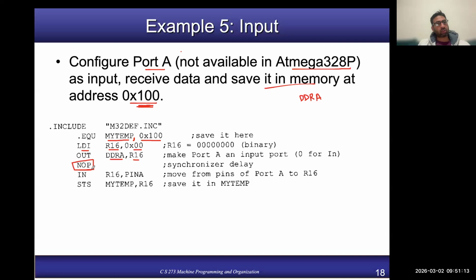So that's why we need to insert one NOP instruction, which basically means putting a delay of one clock cycle. And after that, you are reading the value which is placed in the PIN register, so you are reading that value from the PIN register into R16.